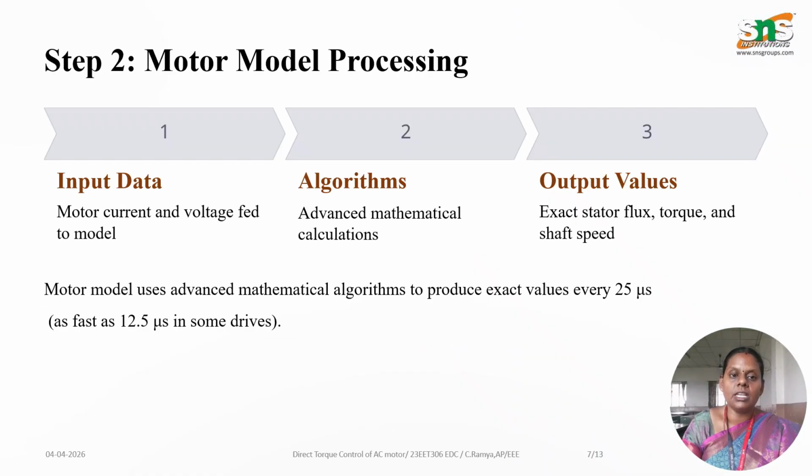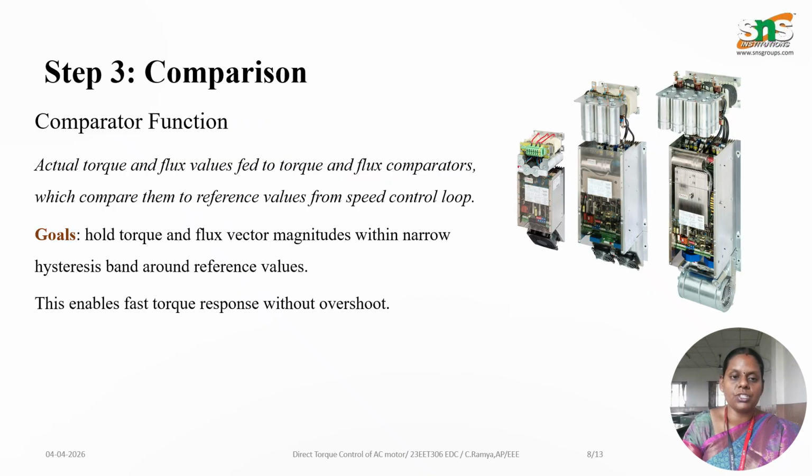And the second one is the motor model processing. In this step, the measured data is fed to the motor model. Advanced mathematical algorithms are used to compute the stator flux, torque, as well as the speed. So these calculations are done extremely fast. Sometimes it can be done within 12.5 microseconds, which ensures precision control.